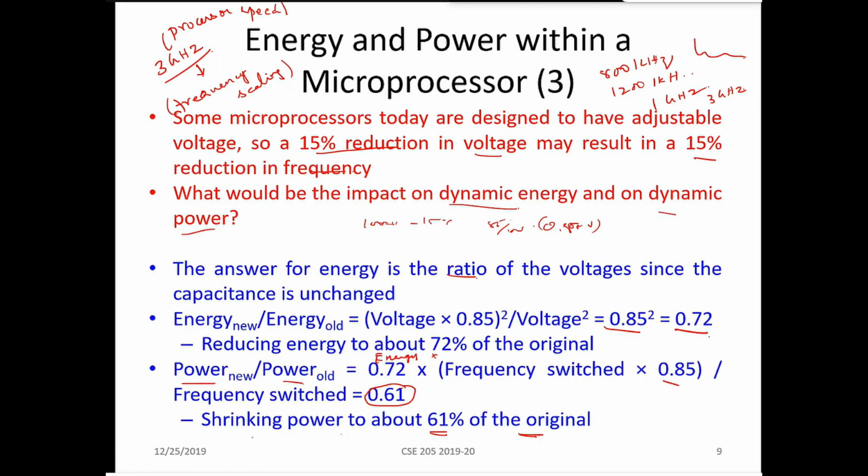But actually, what is happening here? The power consumption will be more. The heat dissipation will be more. But what can I do? Maybe I can reduce the speed of the processor to 1 gigahertz. Thereby I'm trying to reduce everything, the power required, all those things. At the same time, I'm meeting my requirements, executing my task within that deadline. So if there is a possibility, you just try to explore frequency scaling.